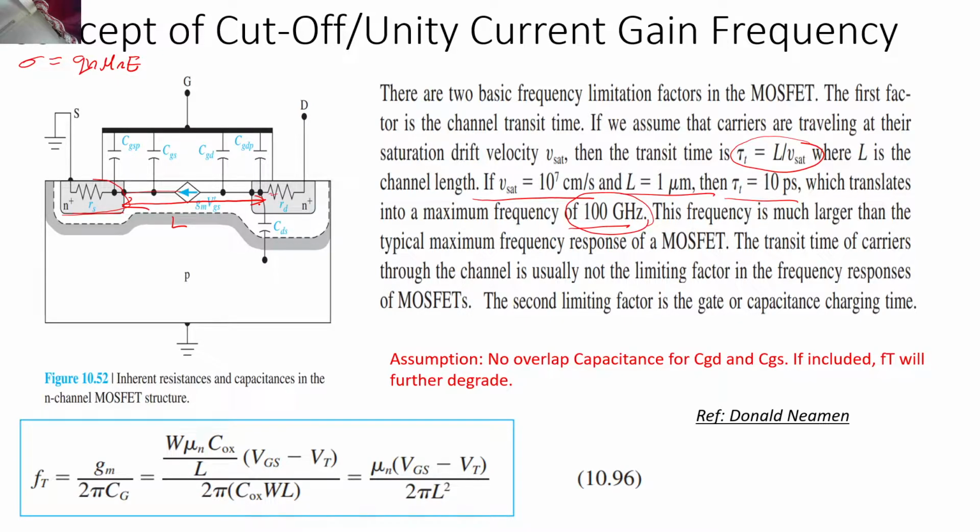Now you have the parasitic capacitances that you know. Your CGS is there, your CGD is there, and some overlap capacitance is also going to be there. Now if I give you a very simple circuit, if you have an R and a C, and you apply a unit step signal, this is u of t. You know this is a low pass filter, so of course the output has to reach a final state, but it will take some time, and this is exponential, correct?